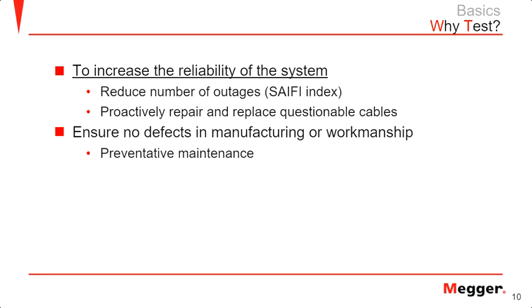Ensure there are no defects in manufacturing or workmanship. So obviously, whenever you splice a cable or you have created a new cable and you're installing new terminations, you want to make sure that everything operates as it's supposed to. It's not like you're pulling the breaker and the next thing you know, it did energize and you have a failure in the cable. So that's something that we don't want. That's why we want to test and make sure everything works before we put actual load on the system.